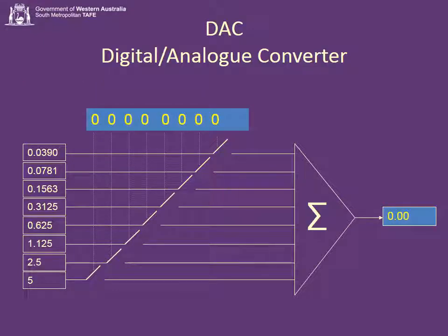So let's talk about how these various things work. First thing I'm going to talk about is a DAC. Now, there is a clever little bit of electronics called an op-amp. That's short for operational amplifier. Sounds very grand. An op-amp is a Swiss Army knife of electronics. It can do any number of different jobs, depending on how you hang resistors and capacitors off the side of it.